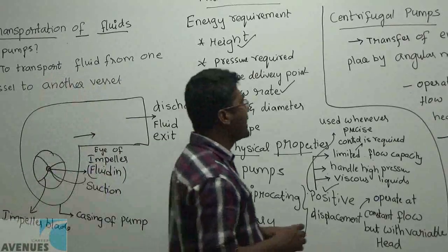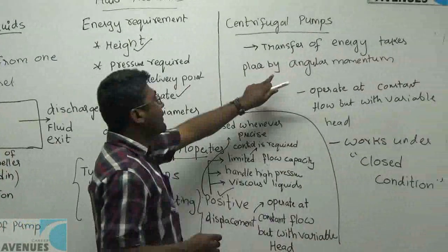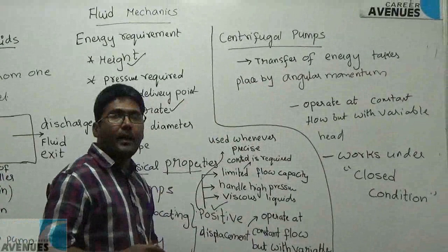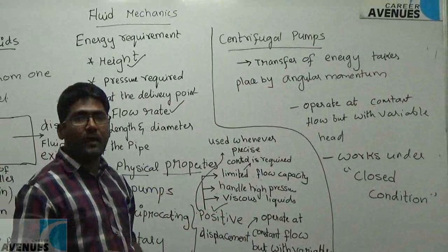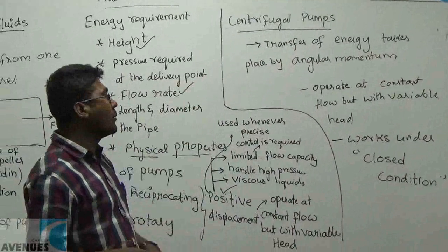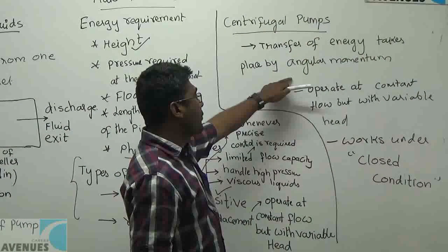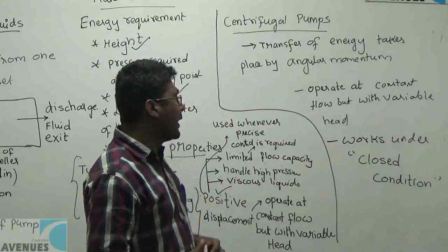Next come the centrifugal pumps. The transfer of energy from the impeller to the fluid takes place by angular momentum. Here it is by reciprocating motion, there it is by angular momentum. These also operate at constant flow but with variable head.